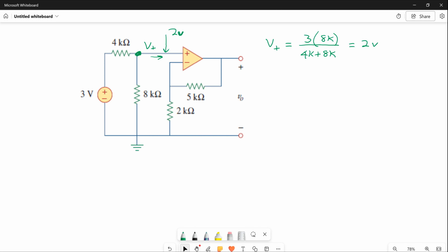That's the voltage you would use to multiply times the gain equation for some of you to get the output voltage. But we're not doing it that way. We're projecting that over to the other side. We're going to project that 2 volts at that point to the other side, which places it right down here, same point, at 2 volts. And then we're completely ignoring the op amp. So what do we have to look at that point? Well, let's redraw it.